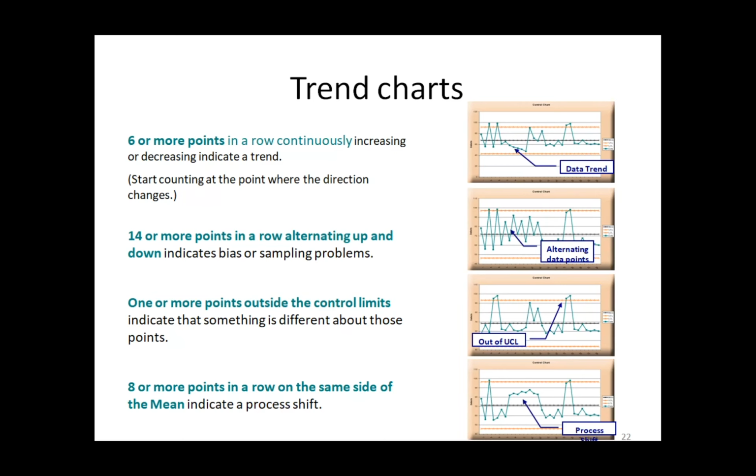The second aspect, as you see here, is 14 points up and down. This cannot be random. It's a trend. Something is happening. The way we are capturing the data may be incorrect, or there are two data points which are getting mixed up. So then we start asking the right questions, and then we uncover some details. And all this can be done using the trend charts, just observing the data, plotting it accurately, interpreting it, and asking the question when it should be asked.